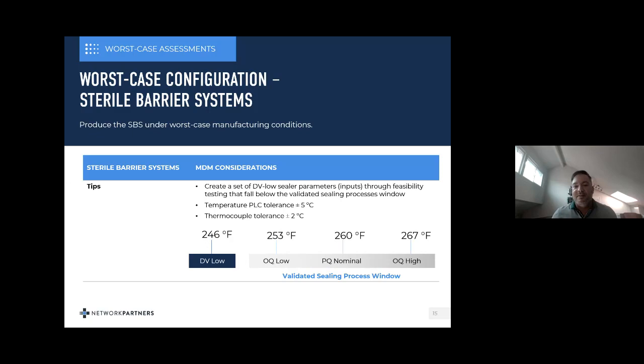The other piece of this is, as you go through your process validation, this is why it's very important to do your thermal process mapping on a sealer with the thermocouples. So you know across the bar that you're getting pretty much the same heat or consistency across that bar. So that'll help you too prior to going into it. So you could take 3, you could take one toward each end, you could take one in the middle, you can combine all the data. But as you really go through and you look at all this data, you're looking for reproducibility and repeatability. So in between each PQ run and across all 3 PQ runs. So you're gonna have a lot of data to statistically analyze to demonstrate this.